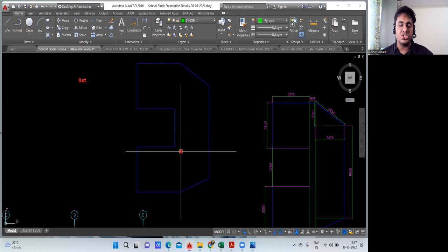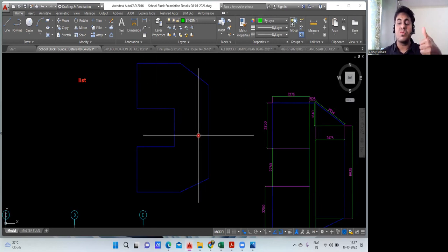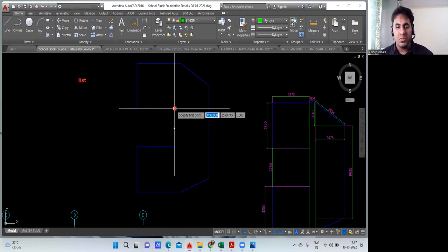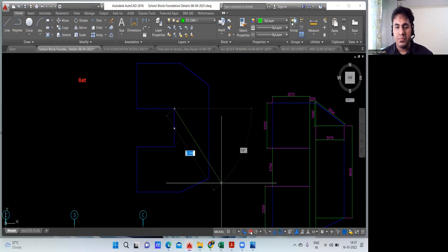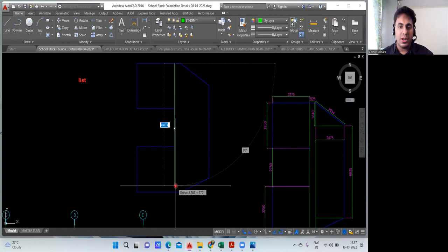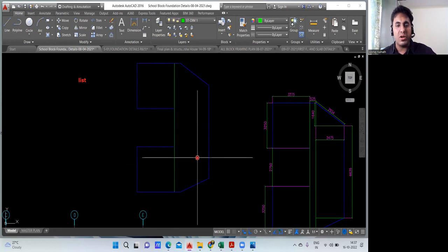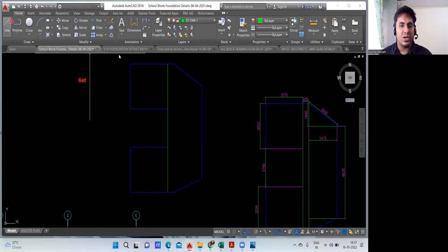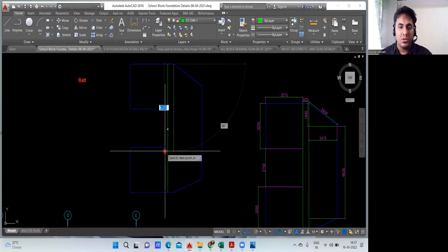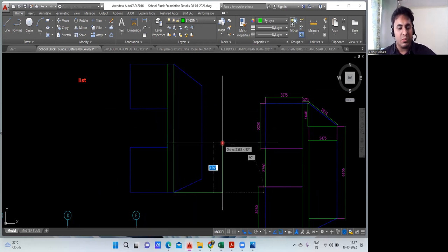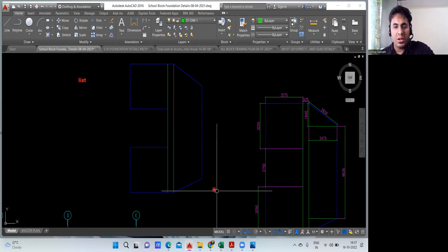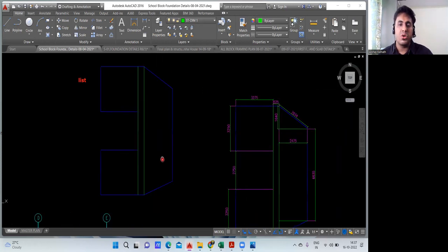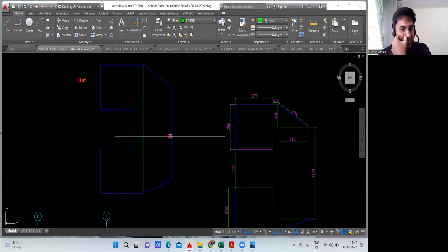Now, this is an irregular shape. I'll try to convert this shape into either a square or a rectangular part. So I'll take a line command from here and make this as one part, this part and this part. Now this got converted into square and square. Then again, here you have a small portion, and I'll convert this portion again from here to here. This is another portion, converted. This is also a rectangle portion. This is a kind of trapezoid, so you can directly keep a trapezoid and apply the trapezoidal formula. That also can be done.